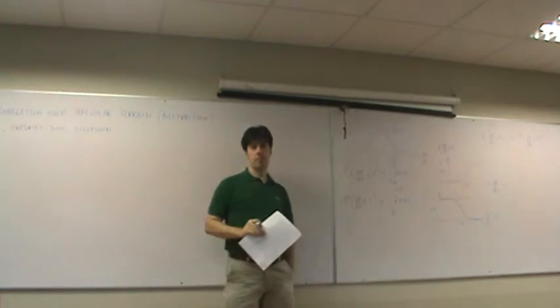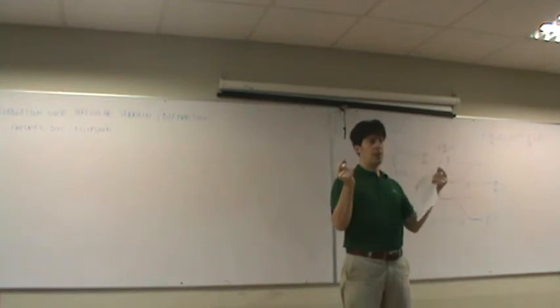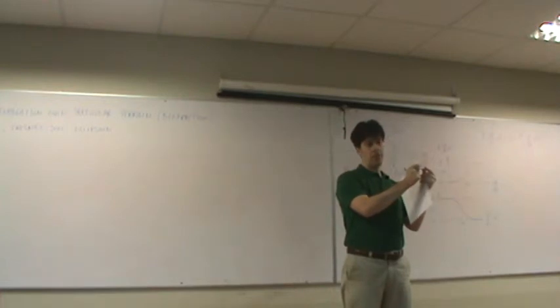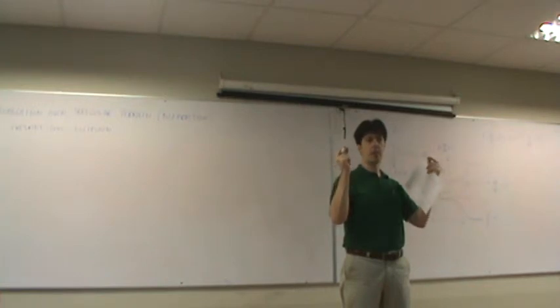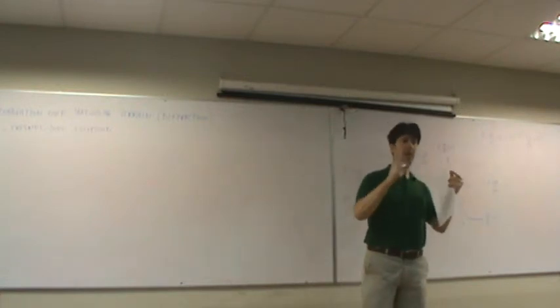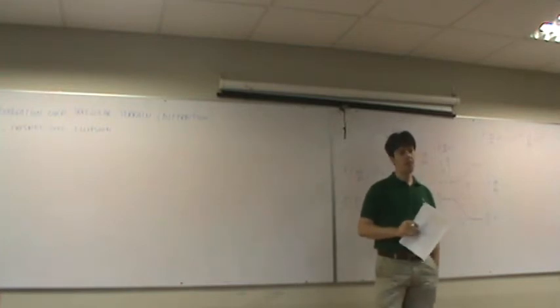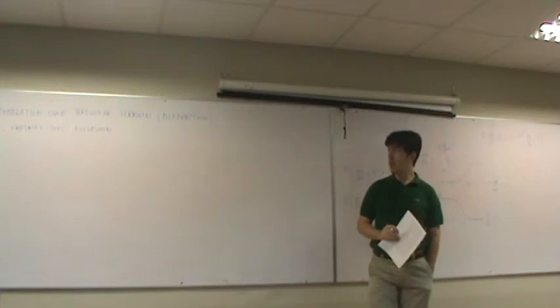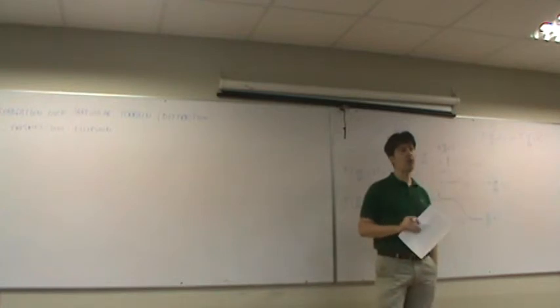This is important because you will discover that when you make a radio link between 2 points, it is not enough to leave the direct path clear from obstacles. You must leave an area around the line connecting transmitter and receiver free from obstacles if possible. This area is called the first Fresnel ellipsoid. And this is most important when you design typically point-to-point links.